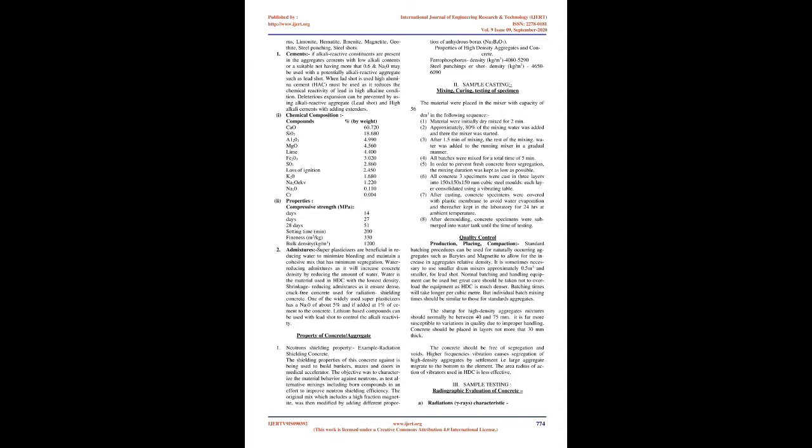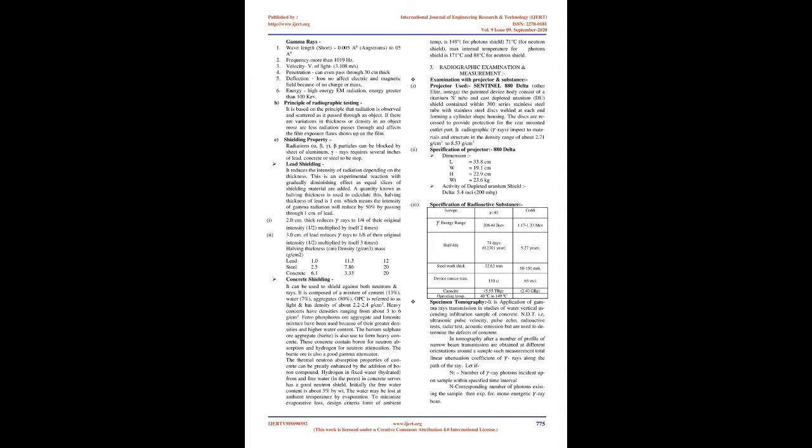2. Methodology. I. Material used. Aggregates. High-density concrete, HDC, is achieved by using high-density aggregates, usually iron oxides. The most important part of HDC aggregates is that the grading should be constant and that a workable grading limit be agreed on with the supplier.